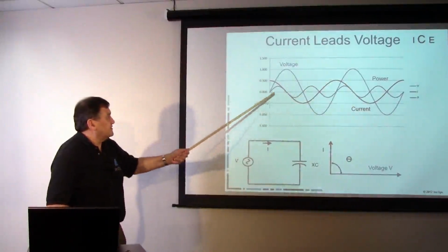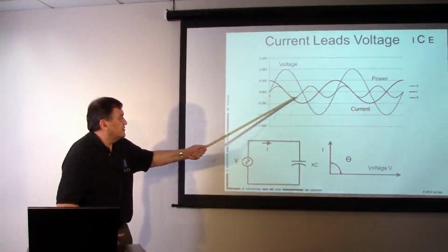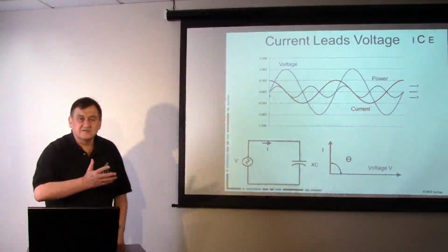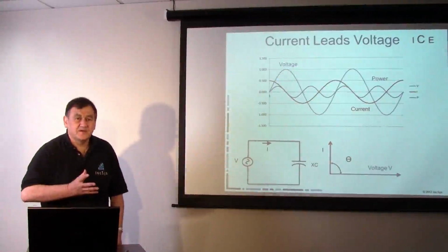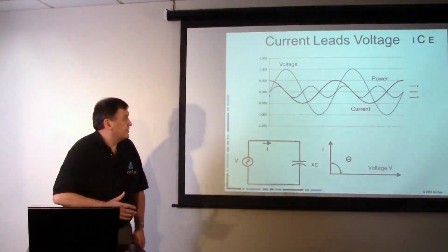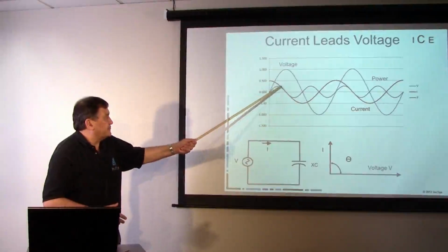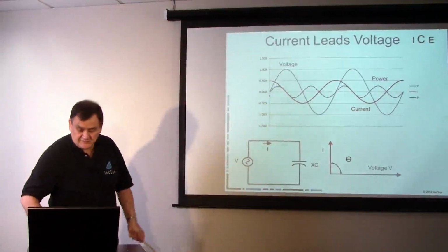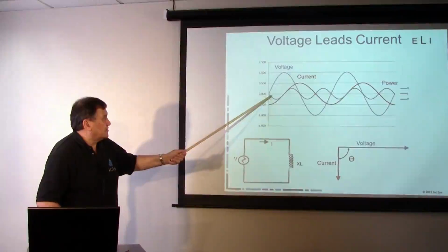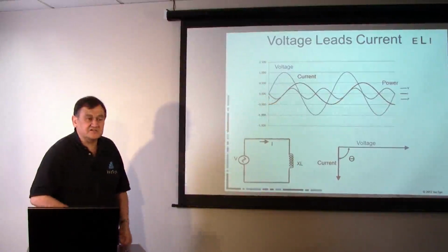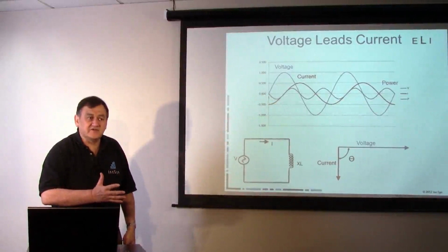The voltage times the current is shown by the purple curve, and this is building up, coming back to zero, and oscillating at twice the actual frequency of the fundamental voltage frequency. And the really good thing is you notice that this power waveform is peaking within the first 90 degrees. And this power waveform with the inductor was peaking in the negative direction for the first 90 degrees. So they literally cancel each other out. And that's why you've got the two parts of the energy equation.